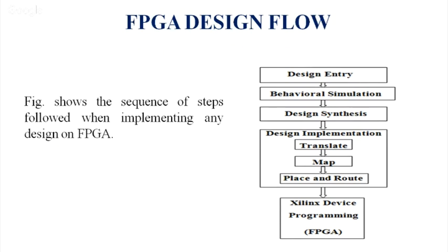on FPGA. For the very basics, first of all, if we want to work on any tool, we need to write a program. So this is the flowchart by which we can burn our logic on FPGA. First of all is design entry, then behavior simulation, design synthesis, design implementation, and then burning our program on the Xilinx device. I will explain these blocks one by one.